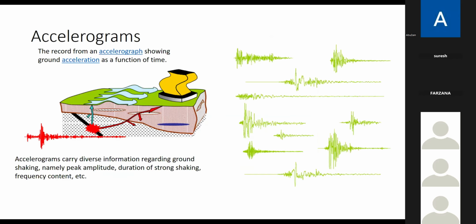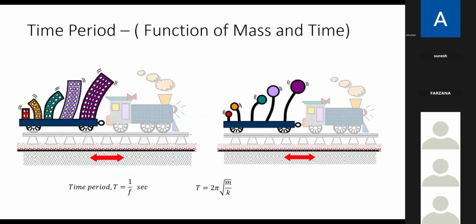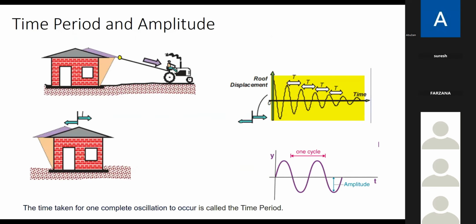I think first slide. Yeah. What we are finding here, experimentally, in this manner, is not the natural frequency. We are finding the damped frequency, which we call omega d. Omega d is equal to, some formulas are there, omega d equal to natural frequency times square root of 1 minus xi square. I forgot. So omega d equal to omega.